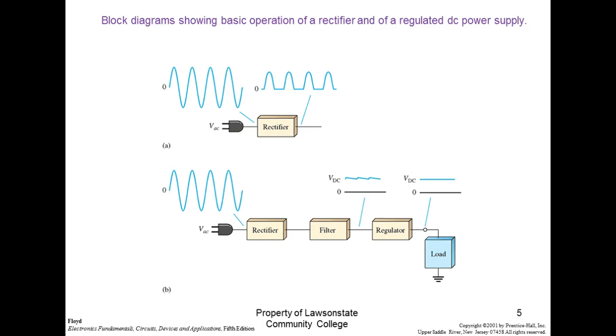But for power supplies, we have two basic types of DC power supplies. We have what we call a linear power supply, which is what we're going to deal with, and it's easy to design and it's easy to fix. So if you're going to build one, this would be the one. And plus, linear power supplies have the ability to produce the most power. The biggest problem they have is that they do not do it very efficiently. So there is a lot of power loss inside the power supply itself.